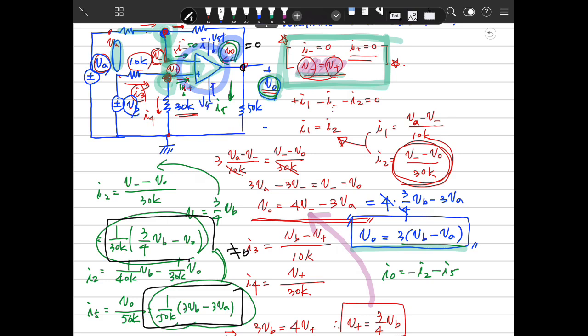So there's some current here. Including this current, KCL is satisfied, because that current is supplied by the two pins here. So in the real model, KCL is satisfied at any point. But in the simple model, because we omit the power supply to the op-amp, you cannot apply KCL at the output node. Don't forget it.